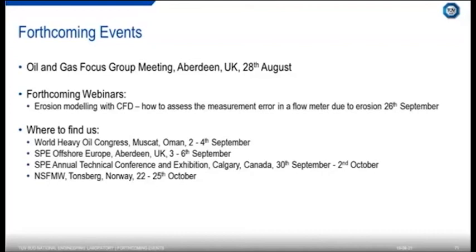That correction was actually developed by a company in the UK. So density is the primary, viscosity is the secondary, and you can tune oscillatory techniques to be either densitometers or viscometers. So you do need to worry about viscosity when you are thinking about calibrating a densitometer. And that's why we had that range of fluids there covering viscosity ranges.